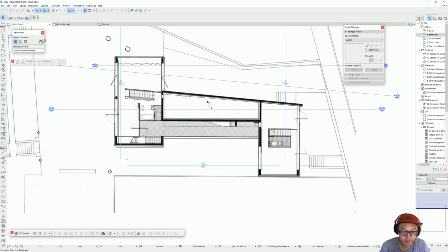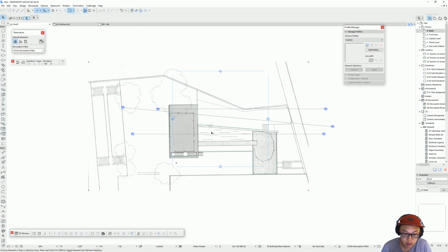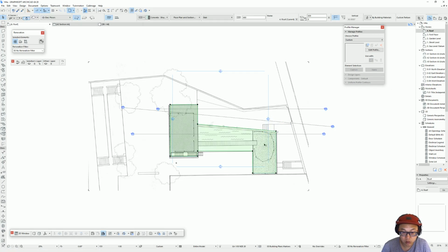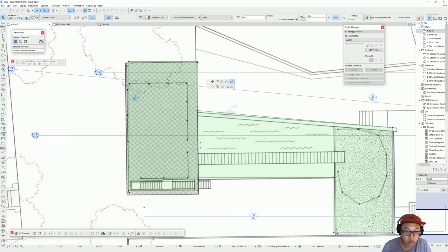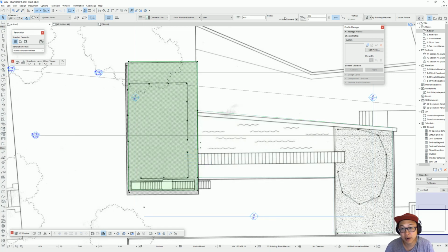I'm gonna just take this, I'm gonna copy, put it on the roof, paste it. I'm gonna paste another one. Take this one first, and I'm gonna, oops, subtract the part that I don't want. And then I'll take the other one, change the geometry methods to rotate it, so I can do it in one go. So now we got the 2 different slabs. This one should be a bit higher. I think it's, we'd say 3.5, 2.5, so we can raise it by 1 meter.